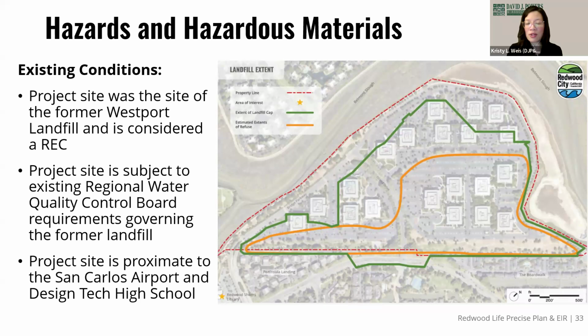The previous Westport landfill on site is a recognized environmental condition, or REC, because of groundwater and leachate contamination and methane gas intrusion on site. No other RECs are identified on site or off site. The project site is subject to compliance with existing regulations governing the maintenance of the landfill cap, landfill gas venting and monitoring system, and leachate collection system on site, as well as land use approval. The existing life science uses on site consist of biosafety level 1 and 2.